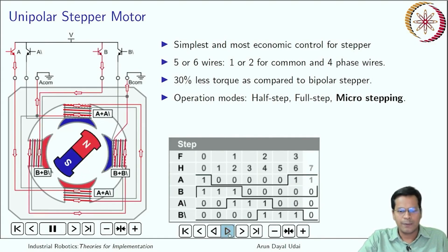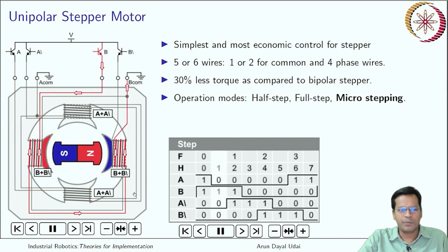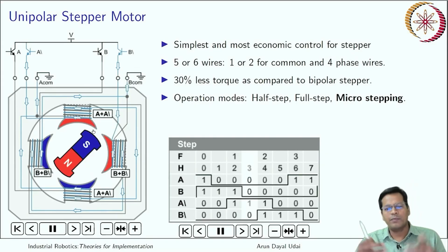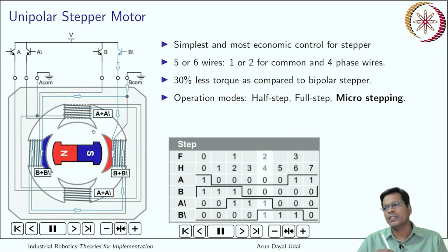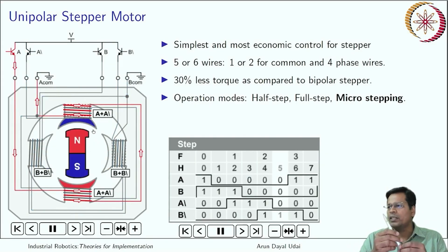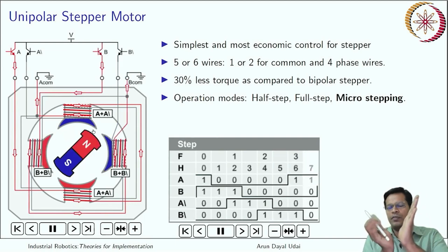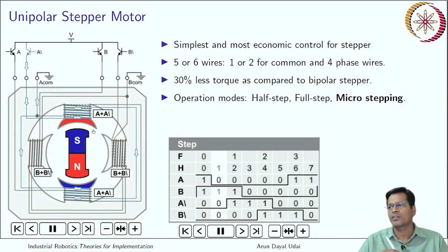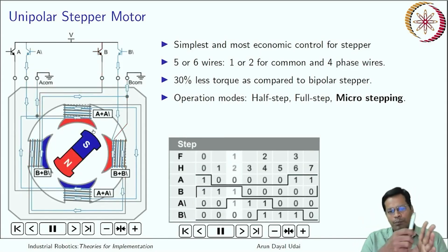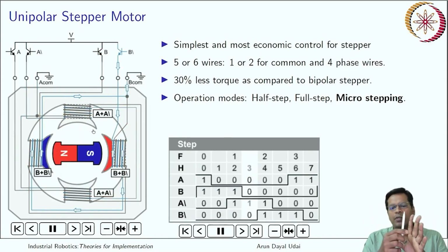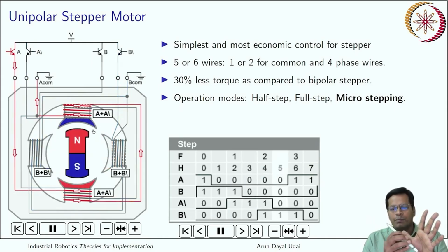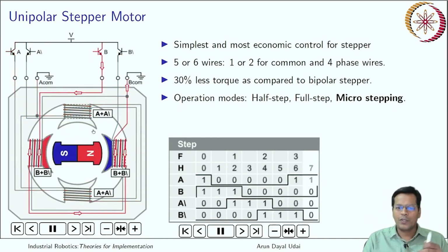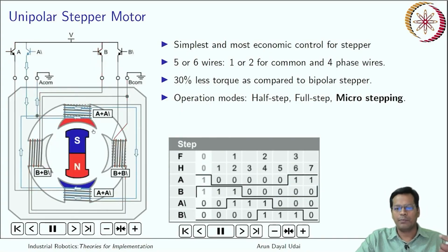So you see how it works, by the time it keeps running we can discuss other things. This type of running, when you have a number of poles and the armature is able to go even to the midway in between, is because of energizing of both the poles simultaneously. So that is half step running. One full step is pole to pole. Half step is pole, half pole, pole, half pole, like that. So it will rotate like this. That is what half step running is.